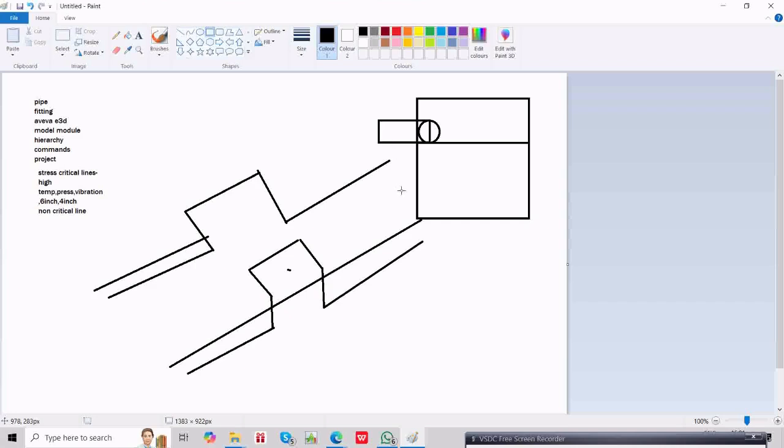You got my point? So regarding the loops, it will be given by the stress engineer. I have never seen an expansion loop used, because for that you need permission from the client. Offshore we can use it. Yes, correct.